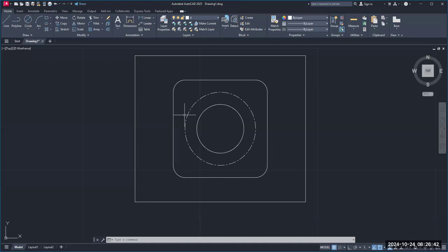We need to draw another construction line, please. So go to line, hover at the center. You're going to hover at the center, click, and we're going to drag a line straight up. Now, notice how I've got too much wiggle room here. I'm not concerned about the length here because it's a construction line. I do want to intersect that circle there.